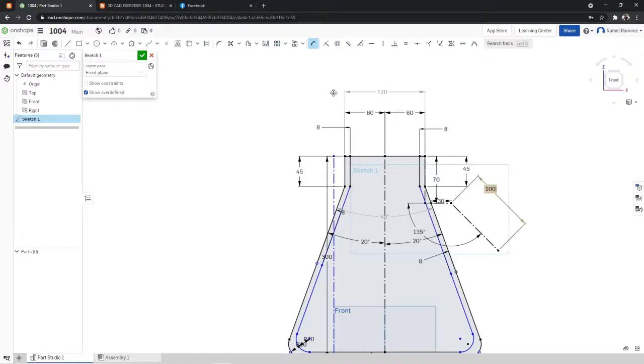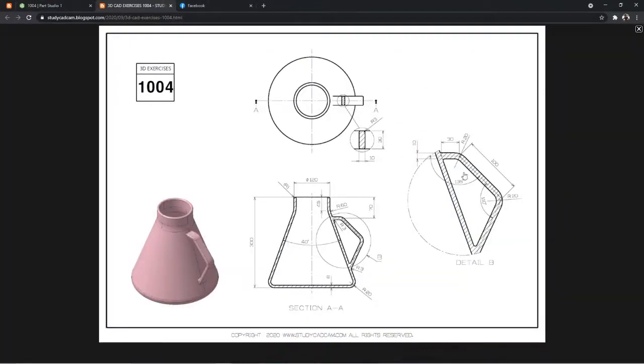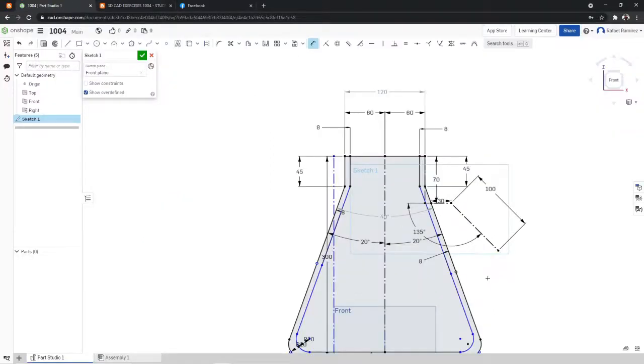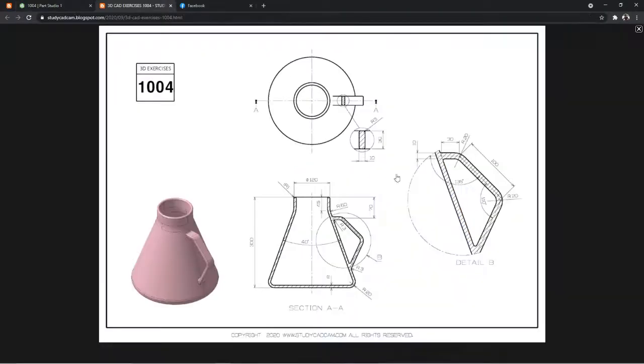Next thing that we would do is, since we already have the 100 millimeters down to the right, the next is another line down to the left. It does not specify here the actual length of this one, so we need to follow the angle as long as we are able to connect this point towards this line. The specified angle here is 110.